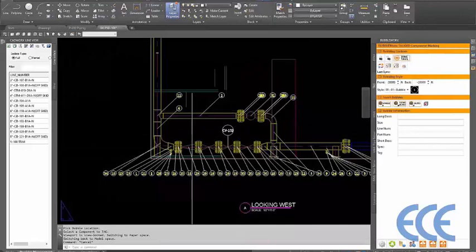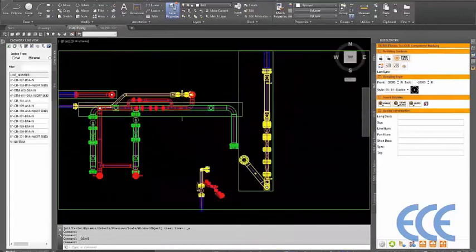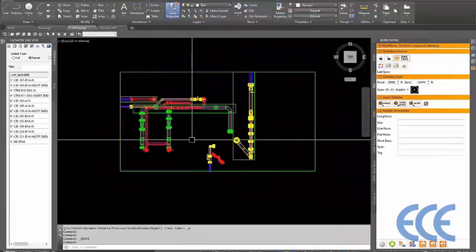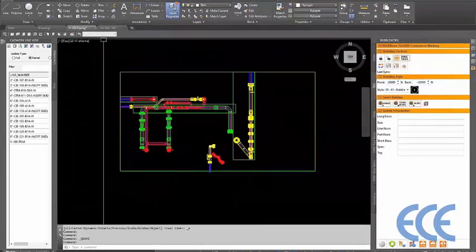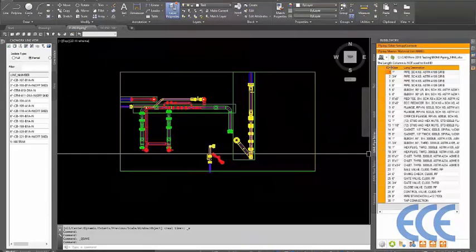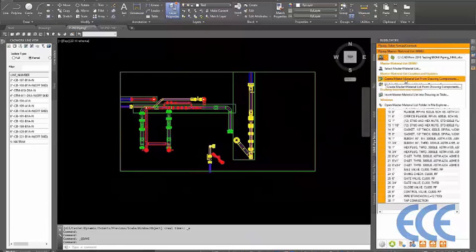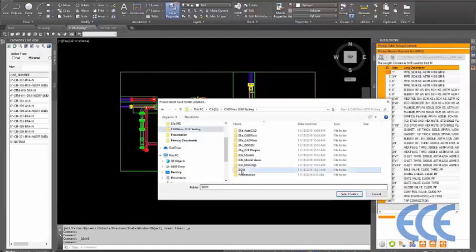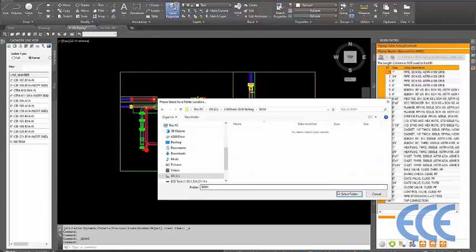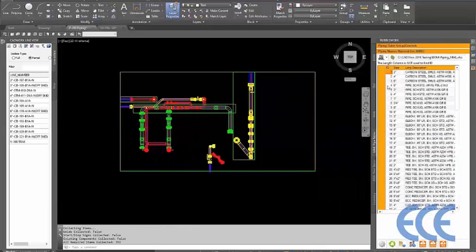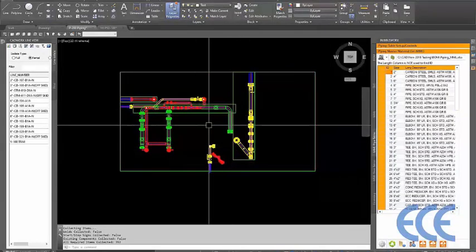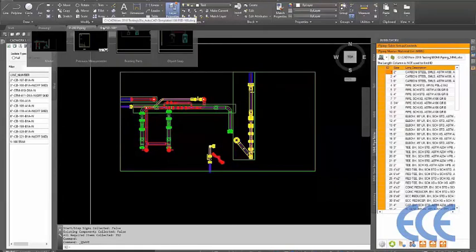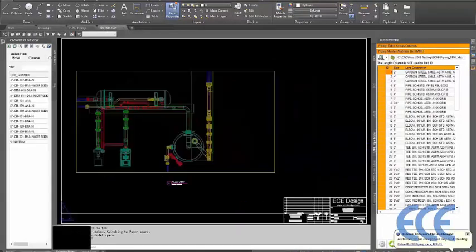Let's go ahead and create a quick master material list here. I'm going to go into my model. A lot of us use XREFs, so we're trying to use these examples going back and forth from XREFs and back into the drawing where the XREF is held. So we can come in here and go to our MML pipe tables, and with the model that we have in here, we'll create a master material list from drawing components. Then we will save it in our BOM folder, because we all keep our master material lists in our BOM or master material folder. And you see this changed here. So now we have a master material list of all of our components in this model. Go ahead, save this drawing, and we will go back over to our existing parts drawing.